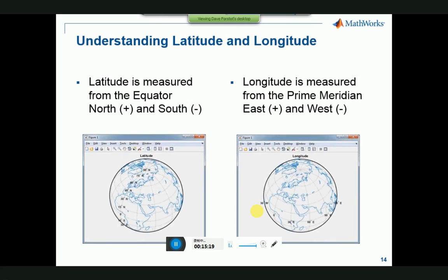So before we go any further, I want to take one quick look. I've mentioned latitude and longitude a number of times. And tying back to that, do we have a question? Our latitude is an angular measure of how far off the plane of the equator we are. So where we define that ellipsoid, that would be the angular distance from the semi-major axes. Does that make sense? I hope so. Now, longitude is actually the angular distance around the globe, and it's measured from, in this case, the prime meridian, which happens to go through Greenwich over here. It's right inside of London.